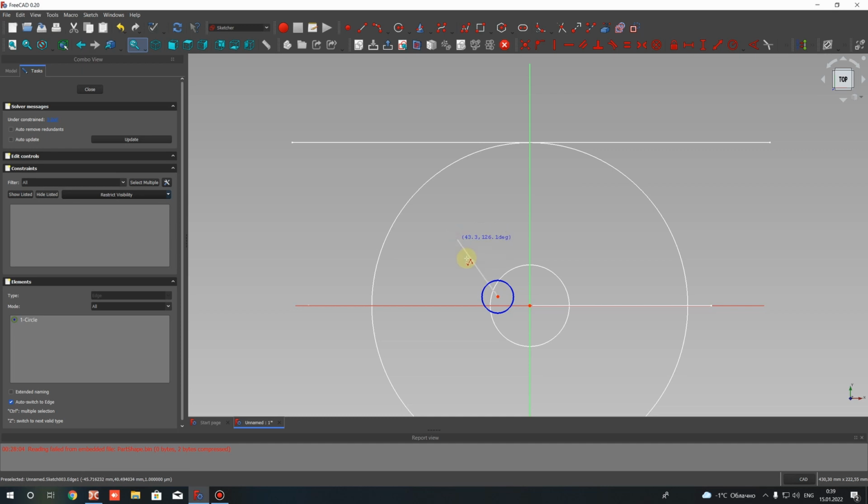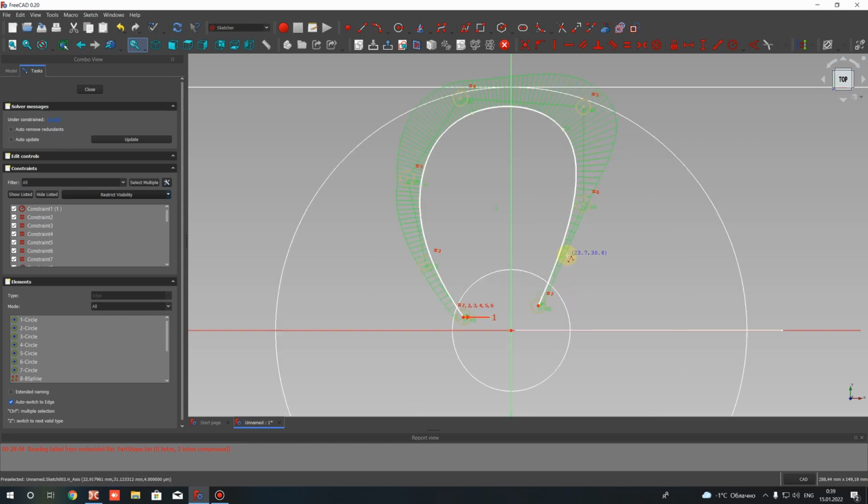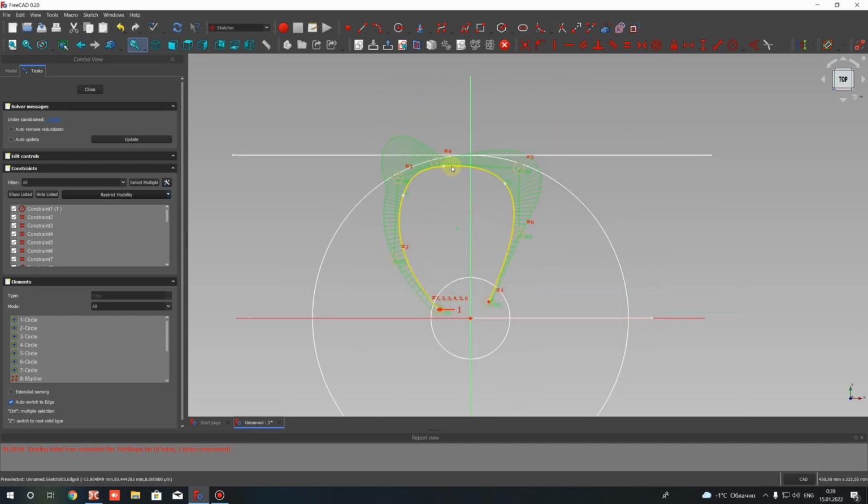I will use several points here, and we will create something like a shape. And when we set all these points, click right mouse, and you will get a parametrical curve here. Okay, I will set it here, and here I will set the shape of the blade randomly.